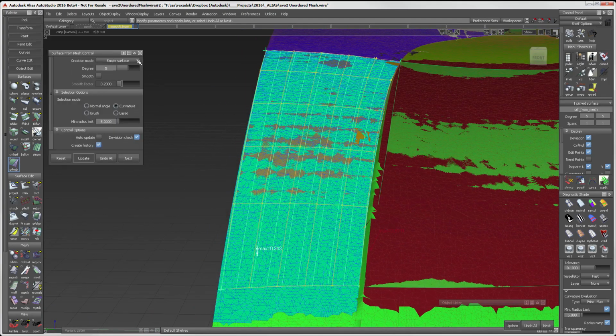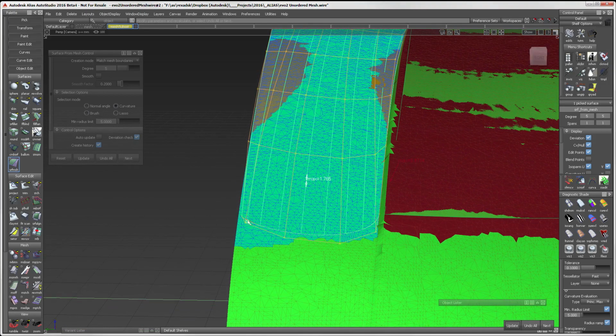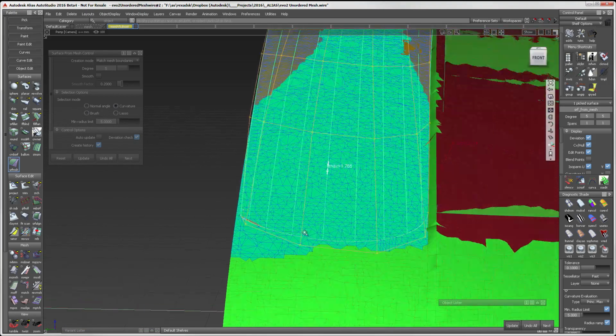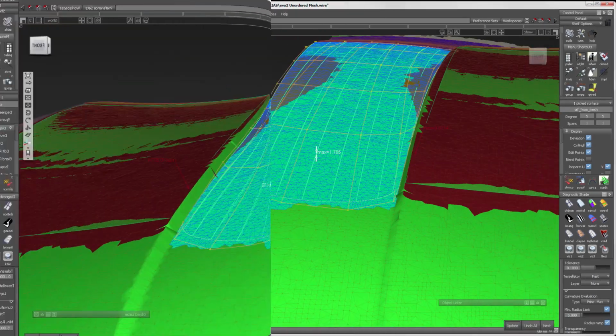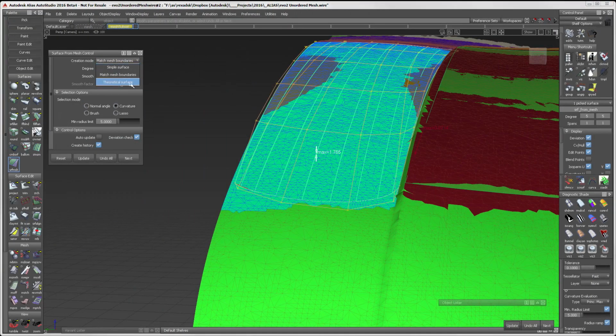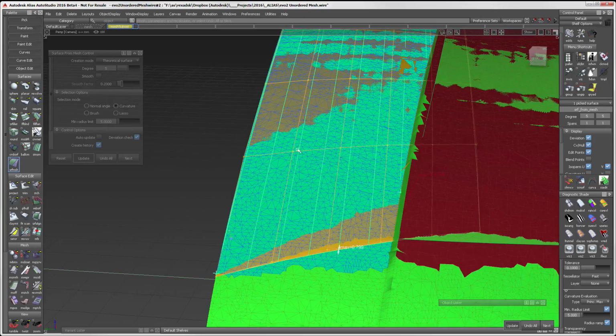The Mesh Boundary Creation mode will attempt to create a natural surface as close to the boundaries of the selected mesh as possible. This is an untrimmed surface, and this works well with tools such as align. The final creation mode is the theoretical surface. In this mode, Alias will build a surface whose boundaries extend beyond the edges of the selected mesh.